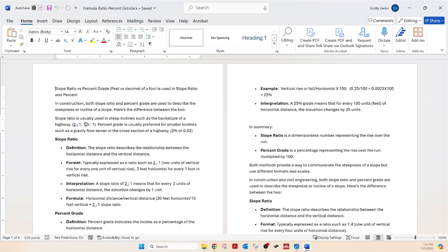But also, the steeper the slope, if it's not solid rock or some kind of type A soil, the more erosion you're going to get, and it's harder to maintain, because a 1.5 to 1 slope, you're not going to brush hog that without tipping over. I don't think. That's a pretty steep slope. But mostly it's to keep it as steep as you can, just because you don't have to purchase much right of way.